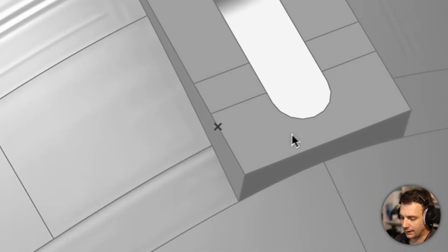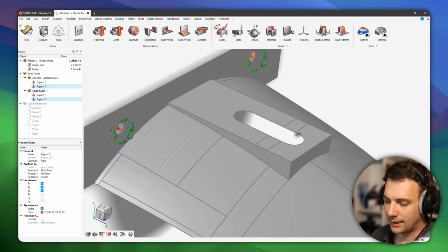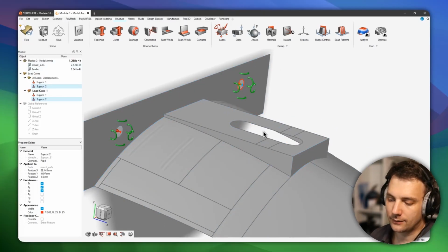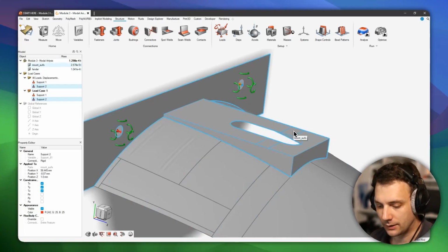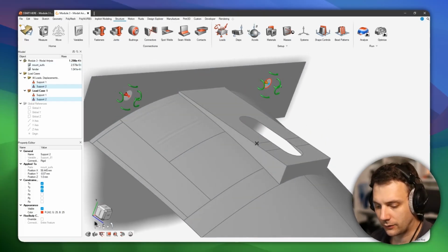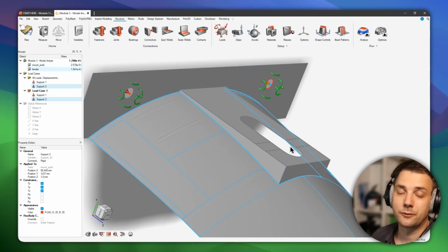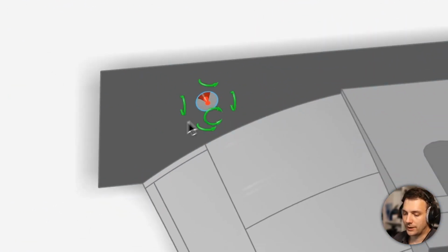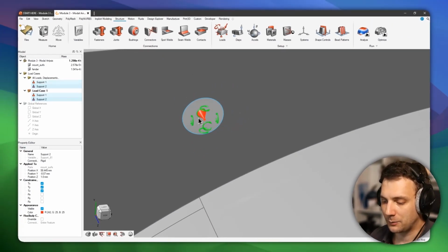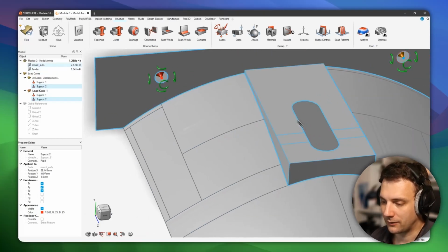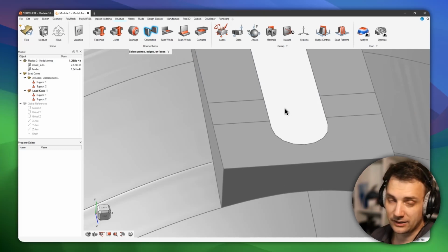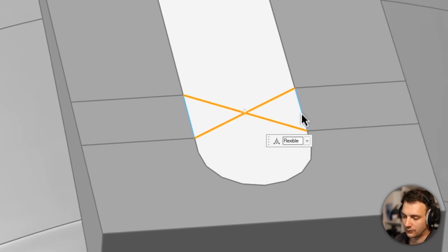The next thing is the area here. And what we like to do is, if that is really mounted to a ceiling, we would like to let also the translation in Z and X direction, you can see it here, Z and X direction, to be free. So in order to do this, we have to do a connector. Same thing, by the way, is being done here, but you cannot see that. But basically, what is being done is that you have something like a connector. And connectors come in 2 flavors. They come in flexible and in rigid flavor. So let's just create that.